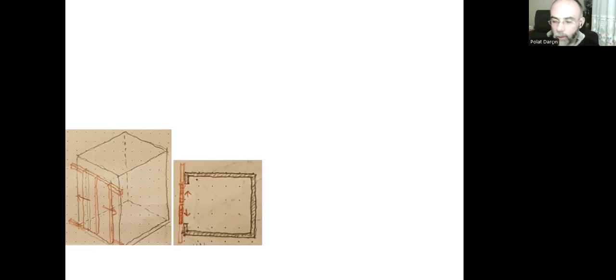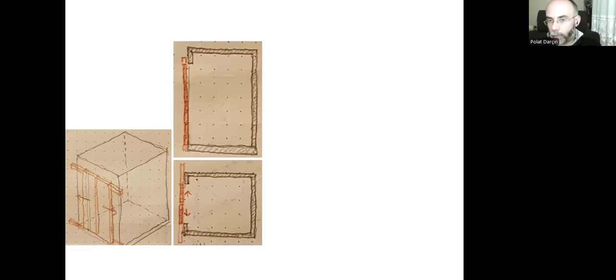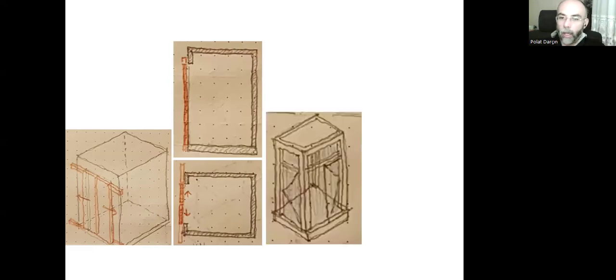The type that requires the minimum size, and that's the section. Again, we cut through the doors. On the plan and the section, we need to draw the doors always closed, not open, and we can have small arrows to indicate in which direction they are sliding. So that's a normal plan and a section here.